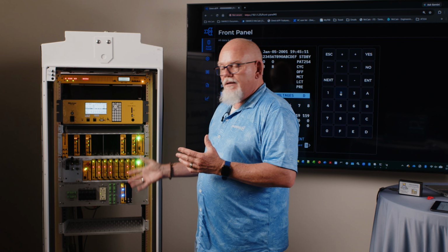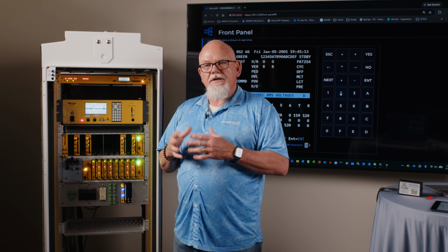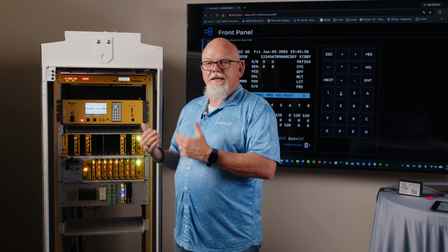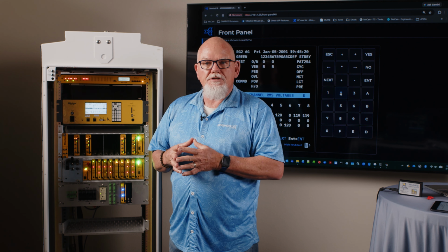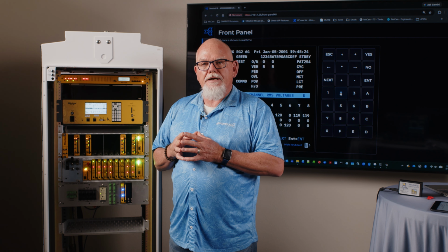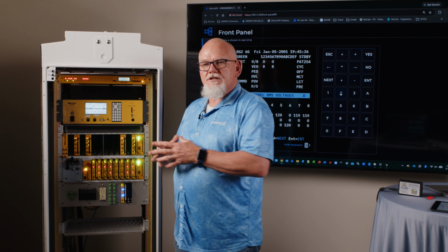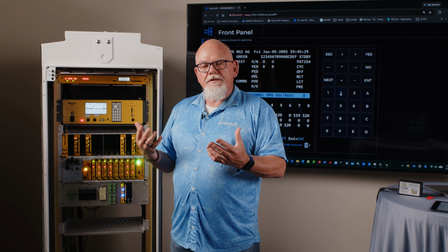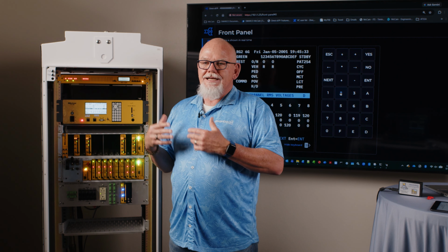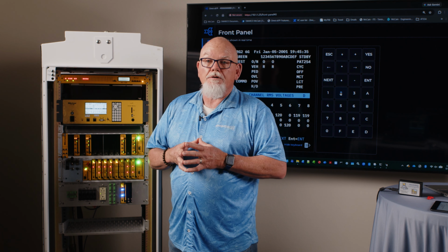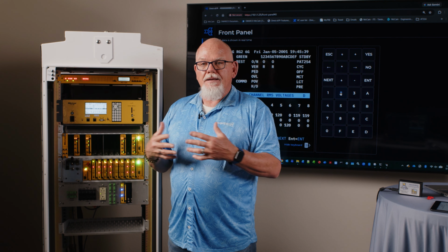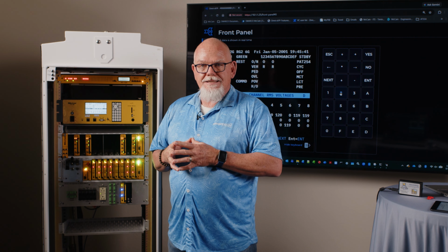As you can see, it kind of looks like a Caltrans cabinet because the ATC standard based its cabinet functionality on the Caltrans 33X cabinet. So very similar in architecture as the Caltrans cabinet. Definitely looks different than the NEMA cabinet, but the functionality that is provided through the SDLC communications in this cabinet came from the NEMA world. So we took the best of both NEMA and Caltrans and melded them together to make the ATC cabinet.